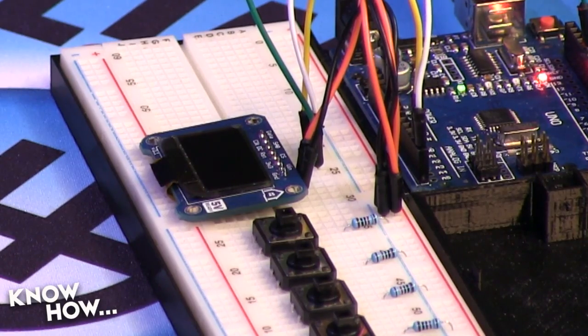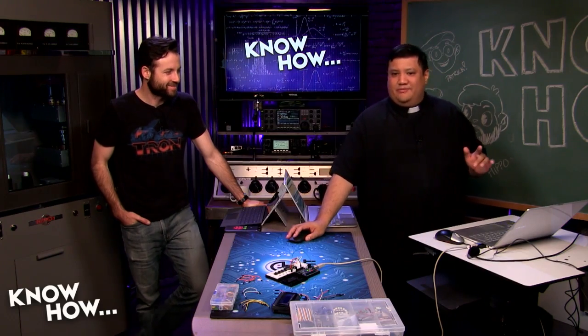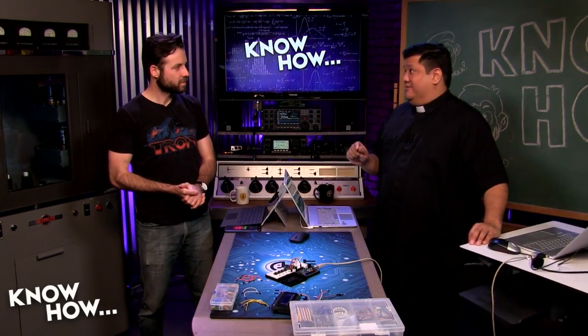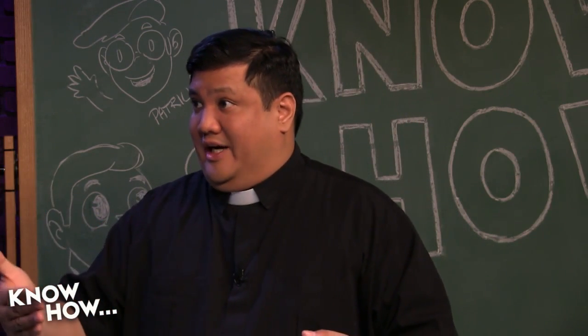Okay, let's do something a bit more advanced, shall we? Sure. Now last time, you remember we had the RTC. The RTC allowed us to keep time, real time. So even if we powered down our Arduino, we still have the ability to know what time it is in the real world. Right, because it had the little battery on the back. But then we also had to make sure when we uploaded our code, we had to upload it a second time with the set date and time and everything commented out.